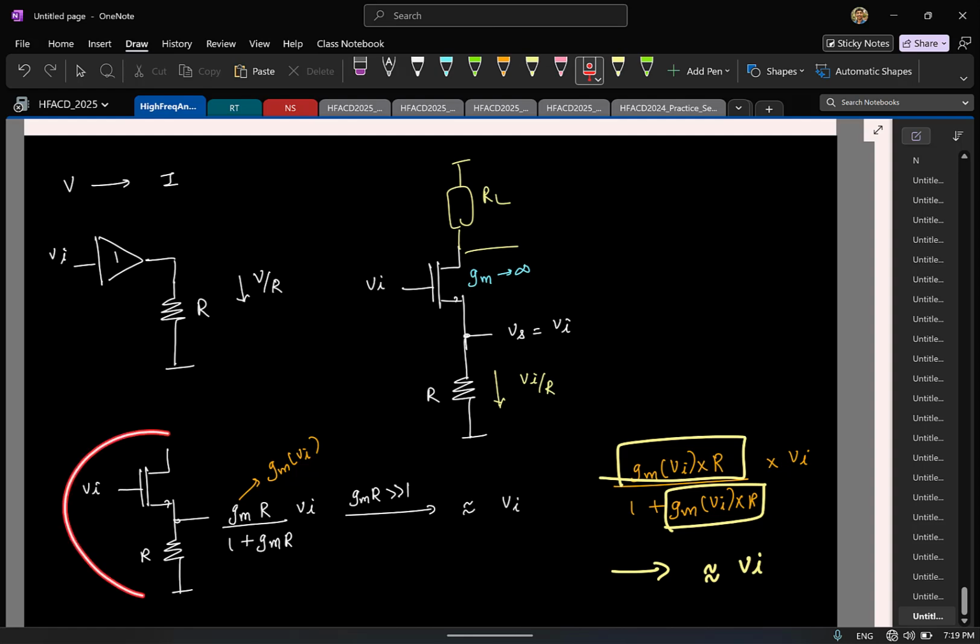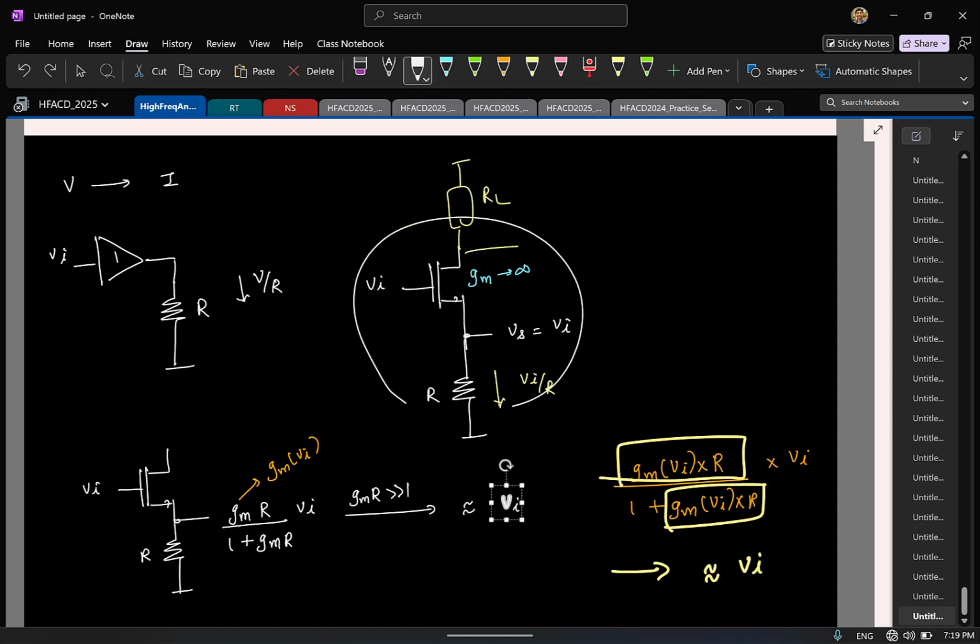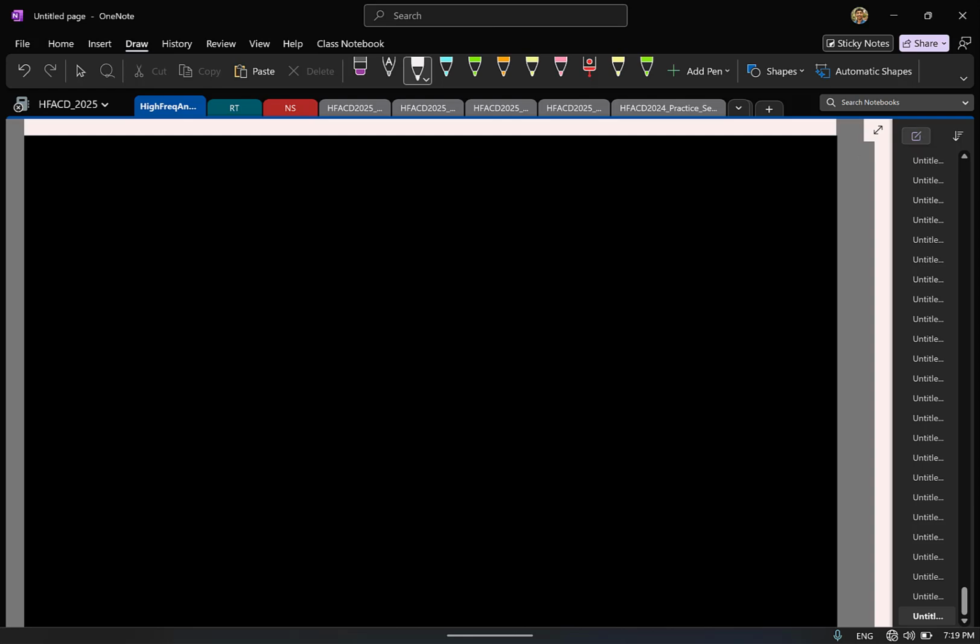Now this is essentially a single-ended picture. Let's try to make a differential amp. Earlier I was converting the voltage to a current using a single transistor. Now instead of that I should have a resistor at the source. One straightforward implementation will look like this.